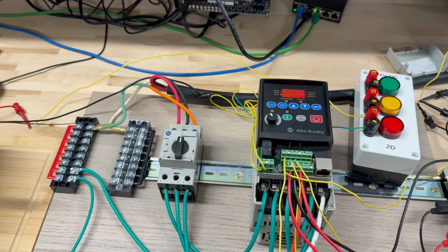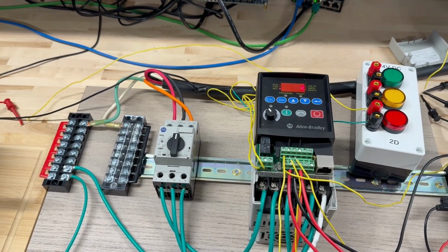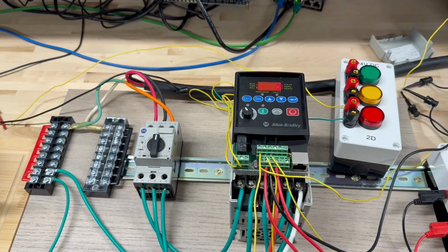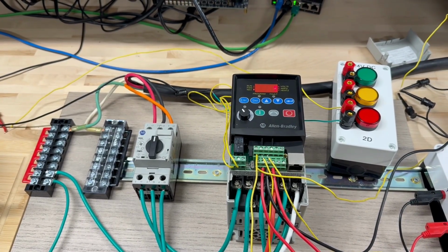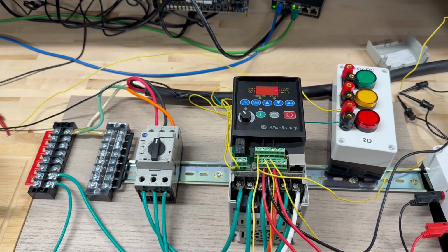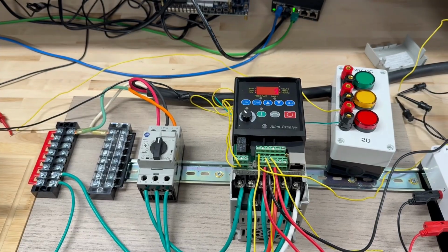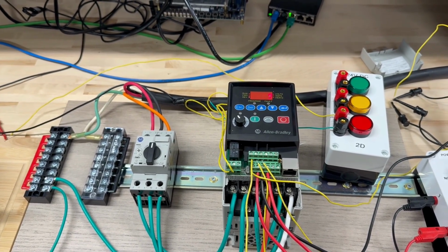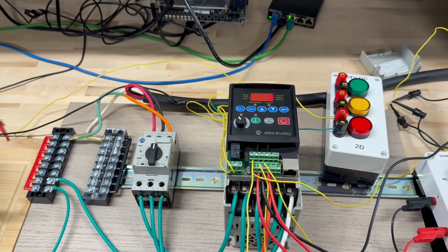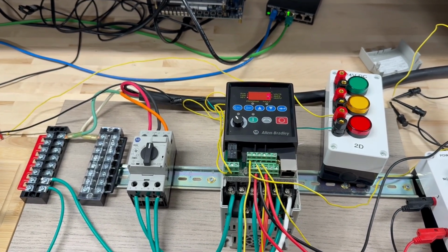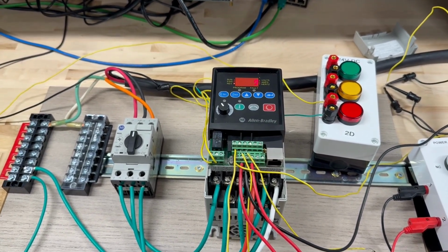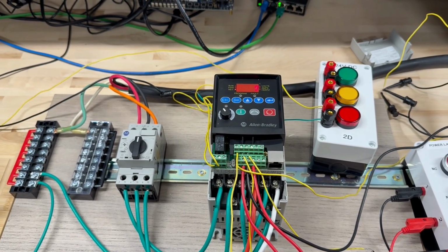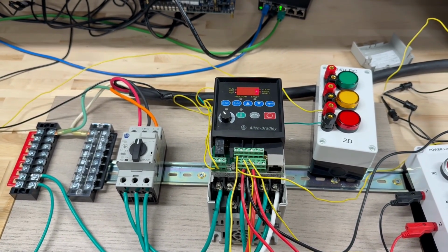What does it mean? If I get the error, the light is not on; it resets the first time, waits 5 seconds, resets. Then again you get the fault, it resets again, waits another 5 seconds and retries. If you get the third one, then your lamp should be on. Technically you say how many retries you have.